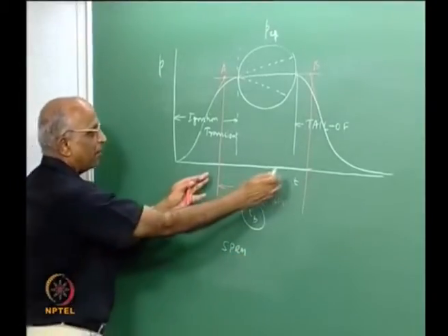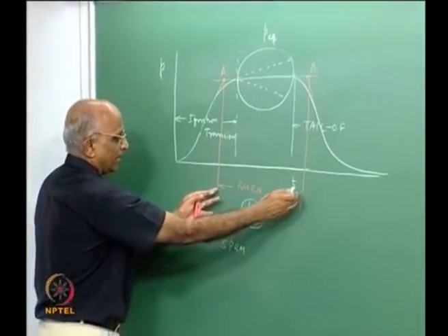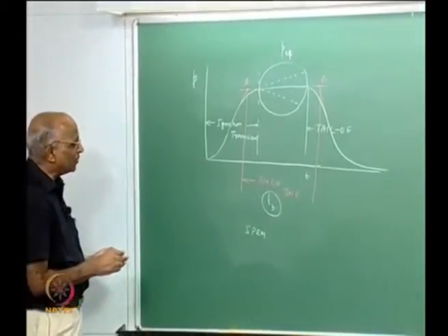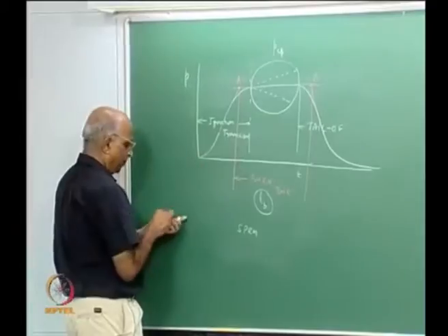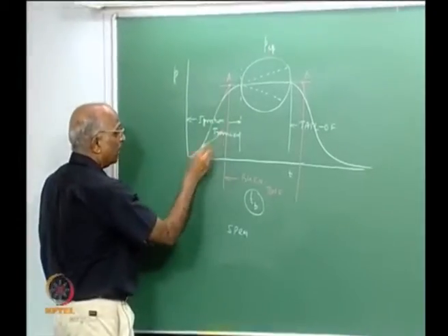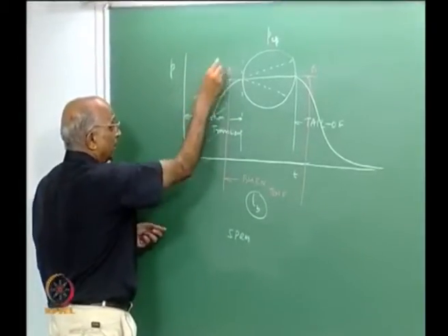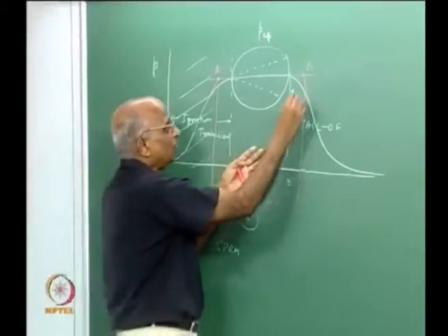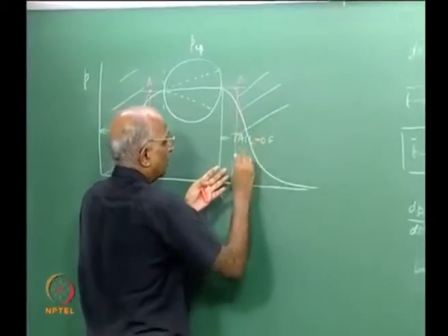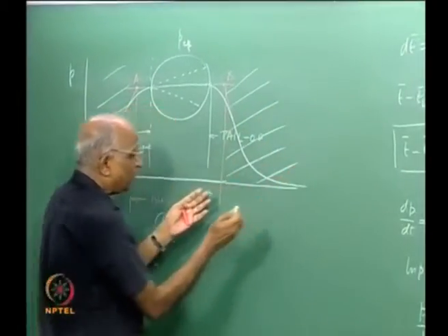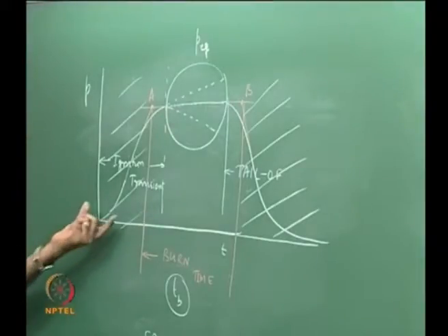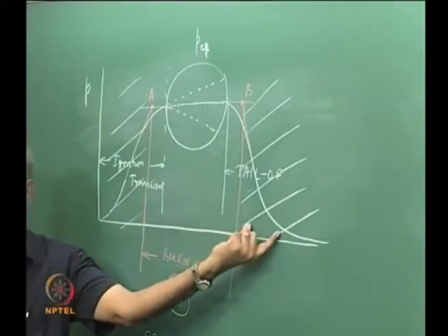We say the burn time of this motor is so many seconds or minutes. But we must also realize that during the period before the burn time, it is still giving you some impulse, and here also you get some impulse. Therefore, when I want to define a mission, to get impulse with which the payload goes up, this also contributes and this also contributes.